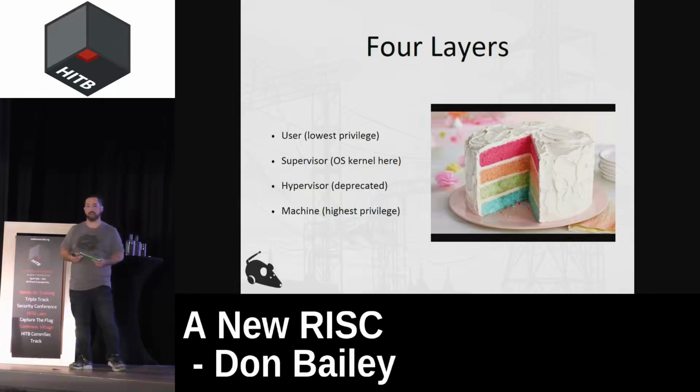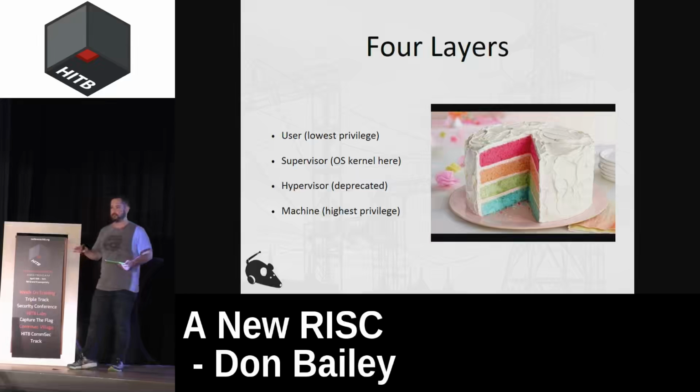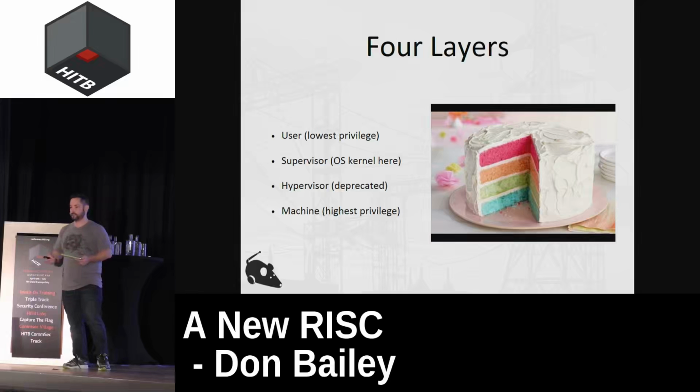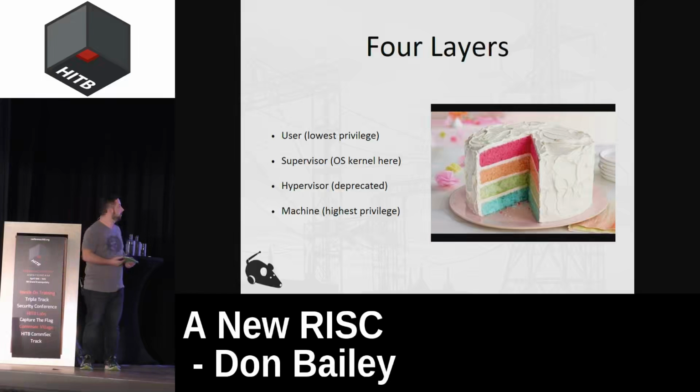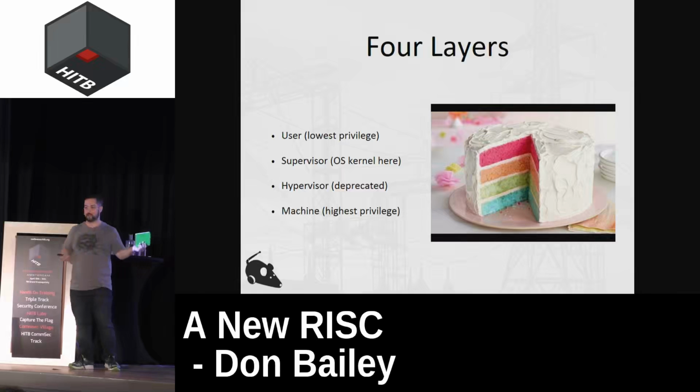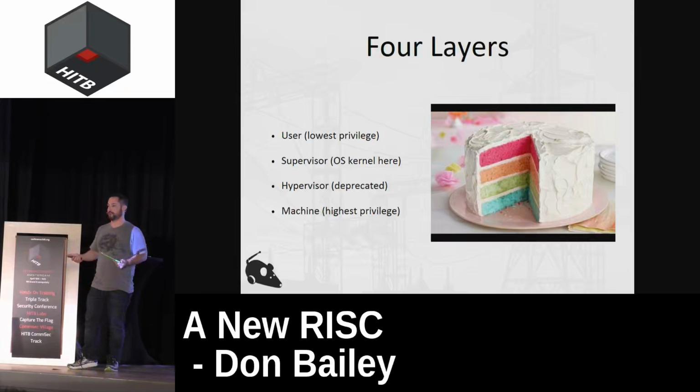So in order to understand the attack that you just saw in the video, you have to understand the privilege model. And I mentioned a little bit about this, right? It's very similar, kind of. I like to think about it in terms of TrustZone, right? So technically in TrustZone, you have a separate area of memory that's quote unquote secure, and code executes there. In RISC-V, the current definition has 4 security models, right? So user land is typical. It's what applications run in. It's what everybody's used to. And then supervisor is where the Linux kernel actually runs, or whatever kernel you're actually executing.